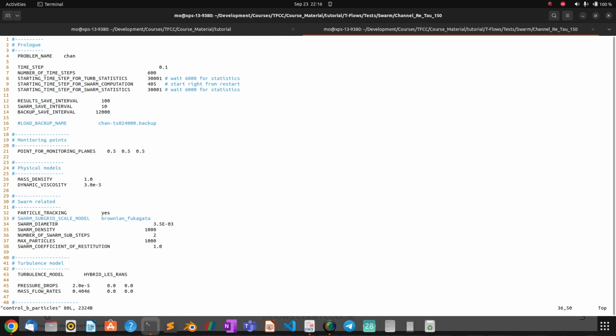It uses half of that, which is 0.05 seconds for each particle. So it advances the particle in 2 steps per flow time step, and that's for stability reasons. That's a criterion that is used in almost every CFD code for particles. But again, it's irrelevant to dive into more details about this; just for you to know that each particle would like to see if it will sense the flow time step or a smaller time step than the flow time step. And by this keyword here, you can